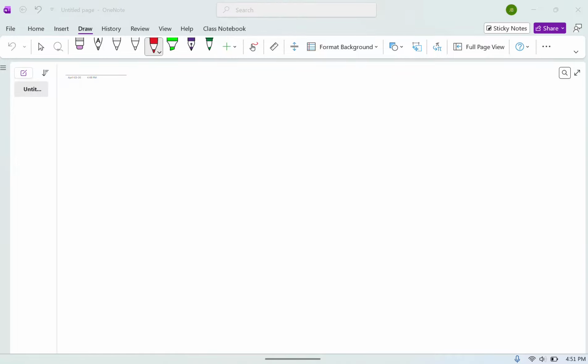So before getting into the air states and the calculations of cooling and heating, we'll first start with the altitude adjustment. We're going to assume that this example is not at sea level, which means we'll have to pick an altitude. So we'll just say for this example we'll have a 1500 foot altitude. So we need to adjust our pressure relative to atmospheric pressure at sea level, with the equation that was introduced in a previous video.